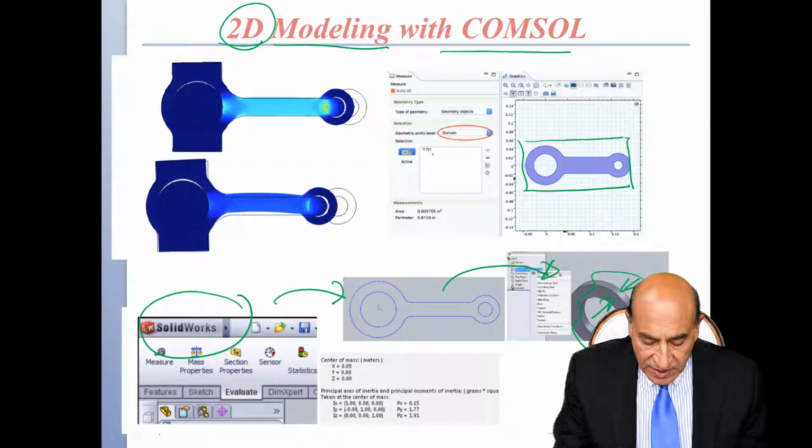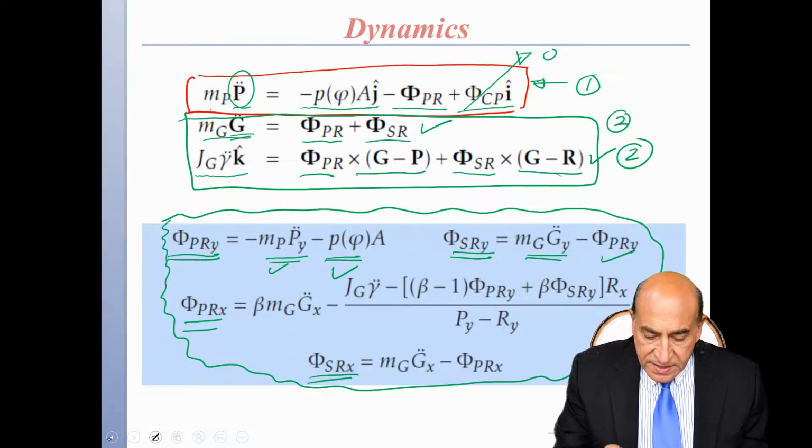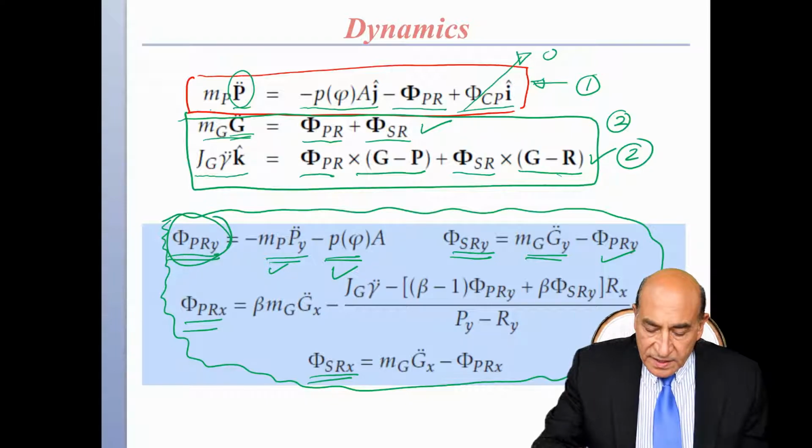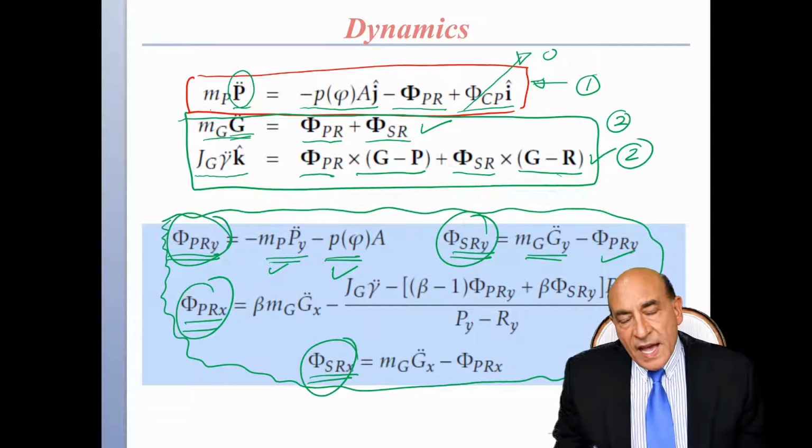So if you look now at the forces on the system, I have these 1, 2, 3, 4 forces and a concentrated torque that would be applied into the 2D analysis to give us the distribution of stresses.